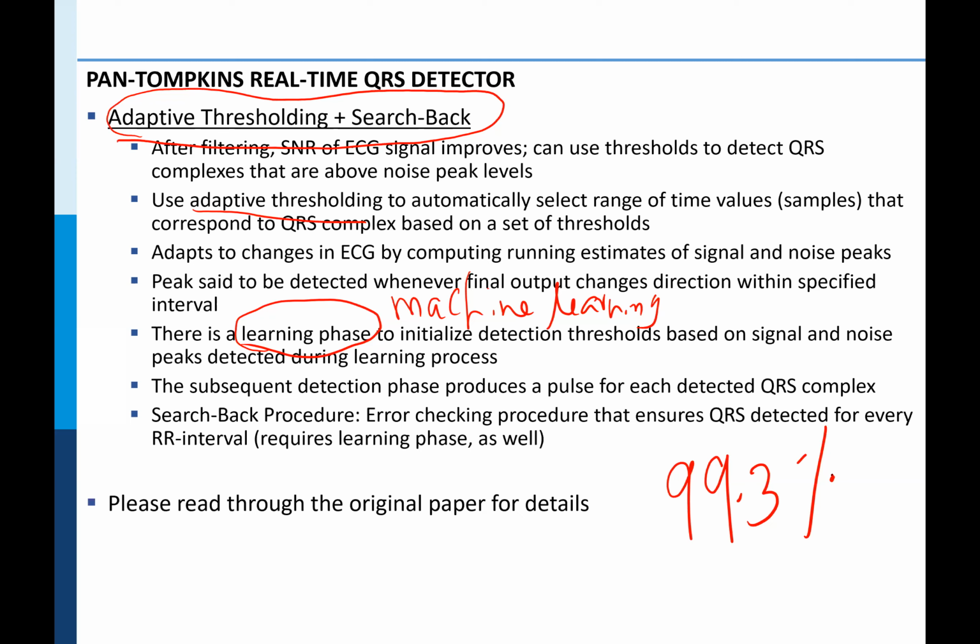So far we have seen a very nice systems view of how different filters have come together in enabling this to happen. And most importantly, the reason why we are happy about this technique is that it has a hardware implementation associated with it. Because the filter coefficients which we saw were all integer values, it allows hardware implementation, and it also gives us fantastic real-time utility, with nothing to worry about regarding the stability of the filter, because there are really no poles outside the unit circle.